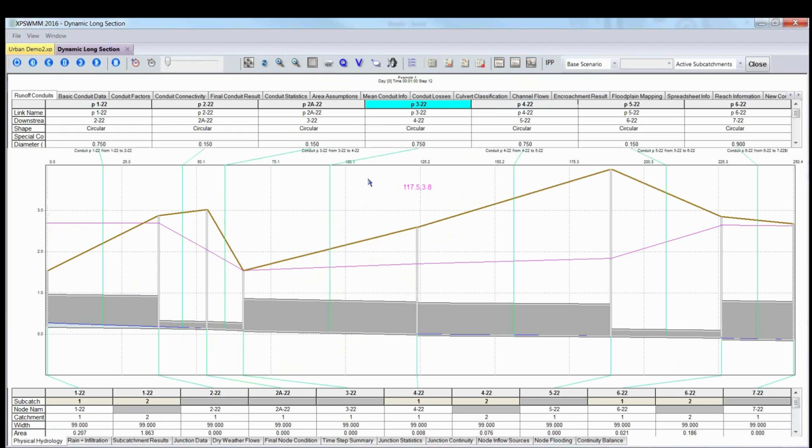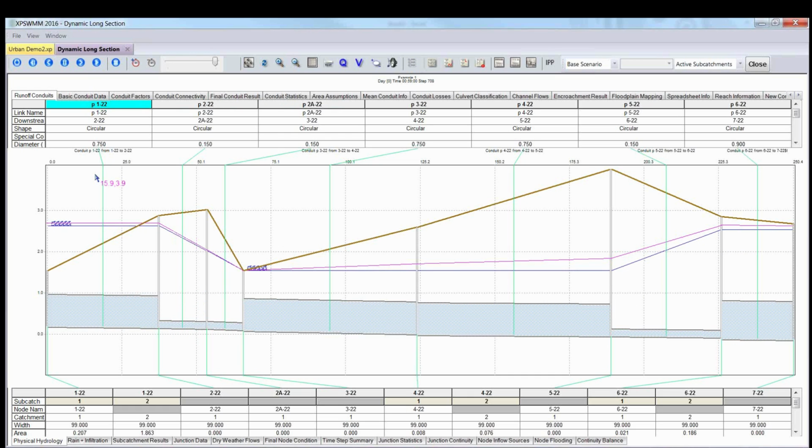And we can see here I've played around with the levels through here. And at this location, this is another point where, by reviewing the output, I can see this model's really got a problem. The 12D input either had a typo or the designer hadn't finished his job before it was passed over to us. And we would most likely want to consider reviewing that inside SWIM or doing a pass back to 12D or your other civil package.